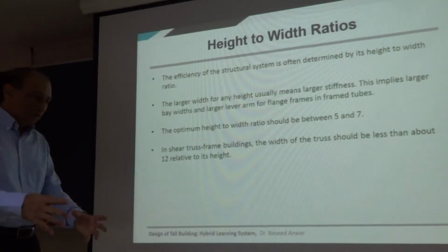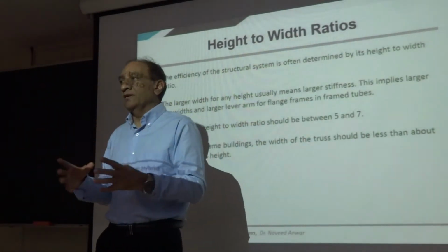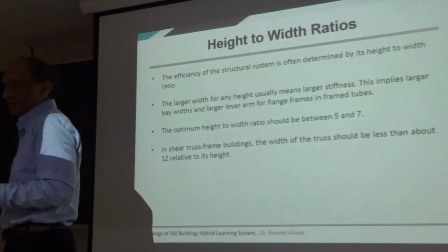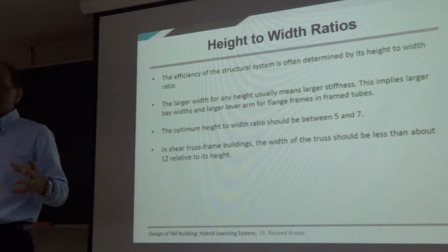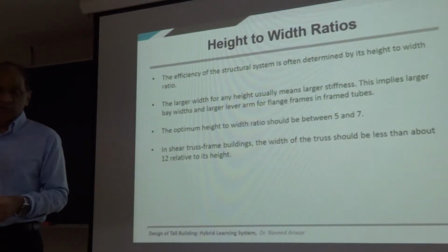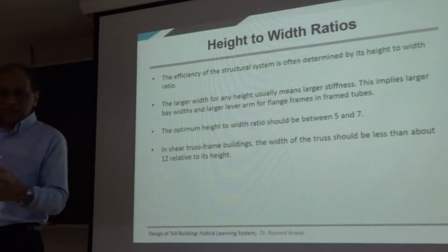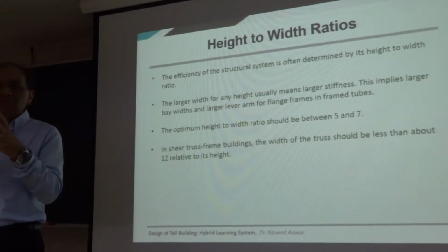So for lower columns, use very high strength concrete, the highest strength concrete your country can produce. The maximum possible, theoretically and practically, that you can get, you should use that concrete strength on the lower floors. Then as you go up, keep the size the same and reduce concrete strength every few floors.